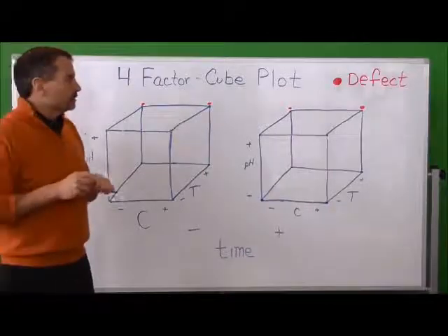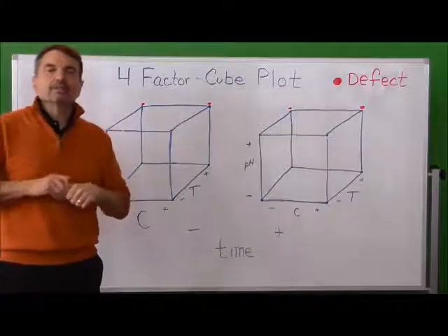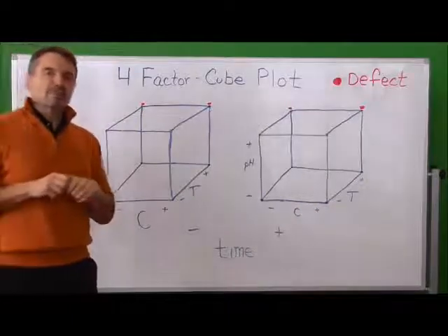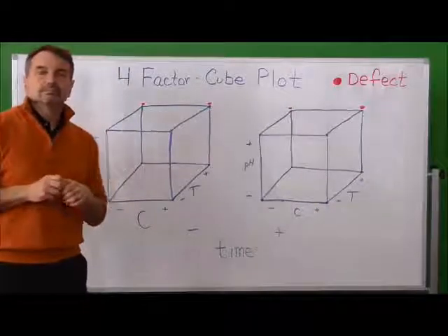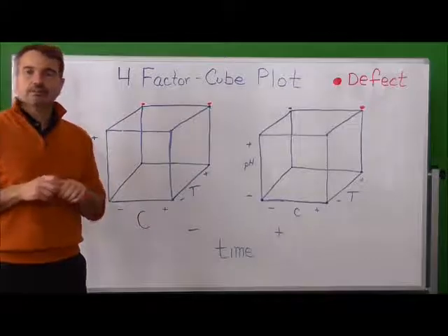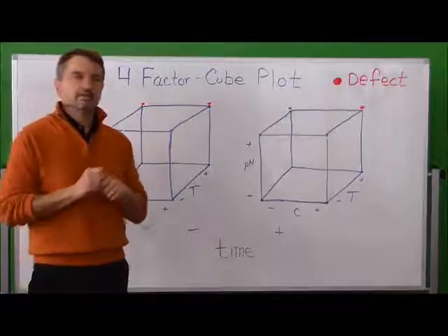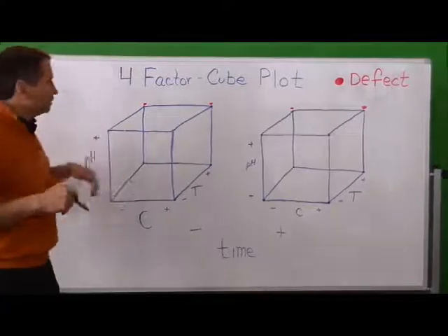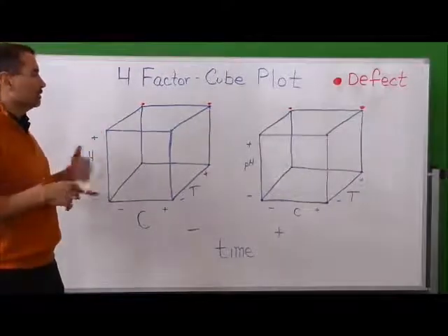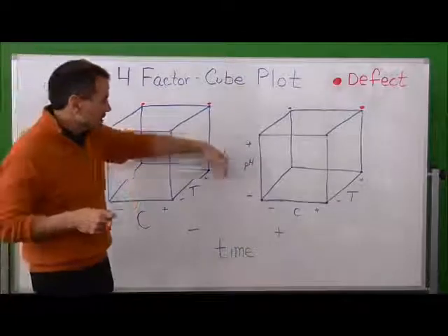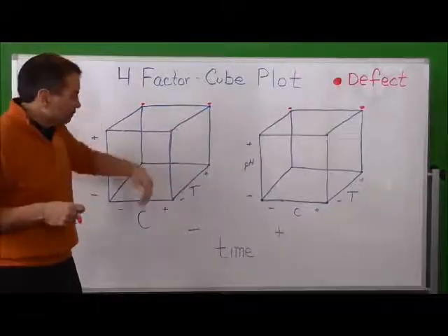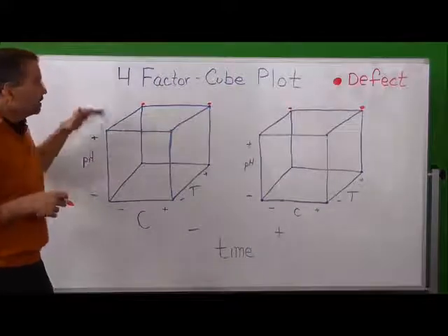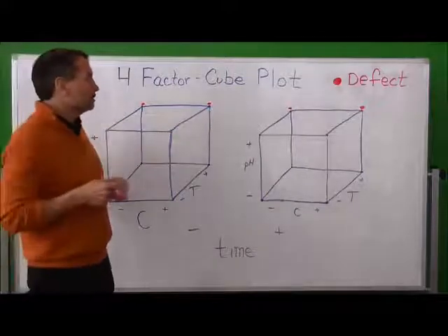Two-way interactions are very, very common findings in design of experiments. If the process is running very inconsistent, it is likely coming from some sort of two-way interaction. Why do we make those statements? Well, let's talk about how it was probably running all along anyway. It probably had a setting that allowed the temperature to fluctuate between 140 to 160, and the pH to float all over the place within a set boundary.